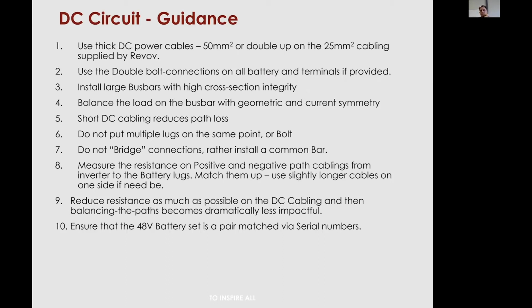But the fact of the matter is, if you just change the measurement threshold, or the Fluke's measurement, I don't know what you call it, bracket, from an ohm to a milliohm, you actually will get a much better read of the two cables and see how they match up.